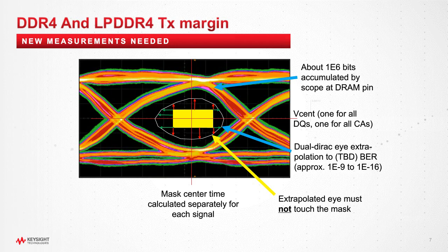So when doing designs with DDR4 and then trying to characterize how reliable your system's going to be, a lot of folks really focus on margin. And of course, you want to have a design that's got margin in it. In the past, margin would be defined by how much actual setup time you're providing beyond what the spec requires and how much hold time you're providing, whether your voltages are exceeding the VIH, VIL, AC and DC especially. All of that stuff is now subsumed basically within the I mask,